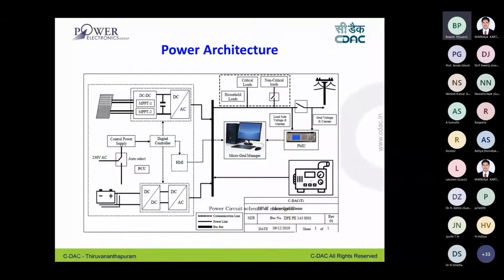So this microgrid manager controls the grid connection and disconnection operations in this microgrid. Here also you can have a critical load and non-critical load selection. When it is working in standalone mode, based on your power condition, you can isolate your non-critical loads when your power levels are reducing. So that possibility is also there in this microgrid.